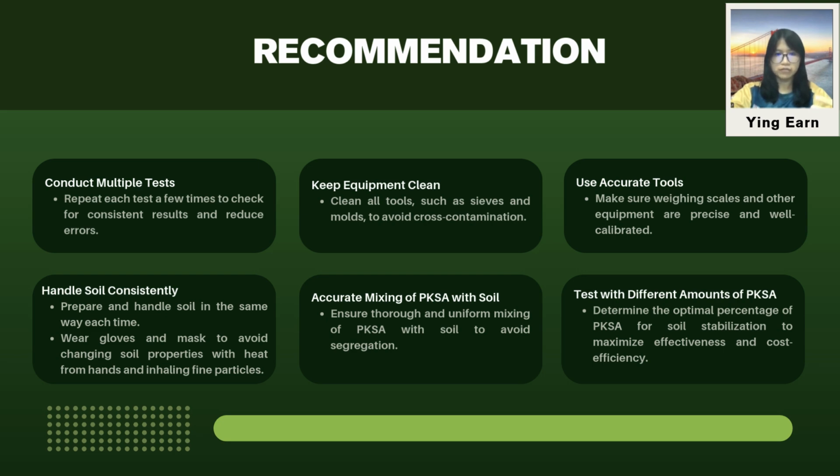Next, we also recommend accurate mixing of PKSA, which is the palm kernel shell ash, with the soil. This is to ensure thorough and uniform mixing of PKSA with soil to avoid segregation and also ensure consistent stabilization.